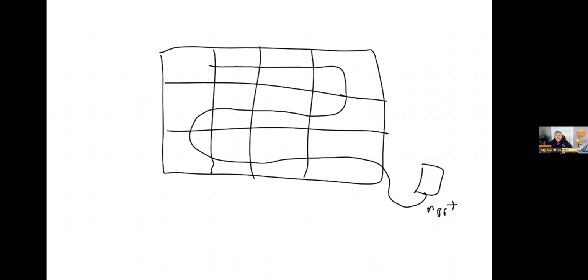Well, what would happen if all of a sudden this panel over here gets shaded? A little bit of shade over here affects them all, because they all function as one unit. Make sense? Yes. So if I've lost some of my power from one panel just because one panel was shaded, it affected every single one.